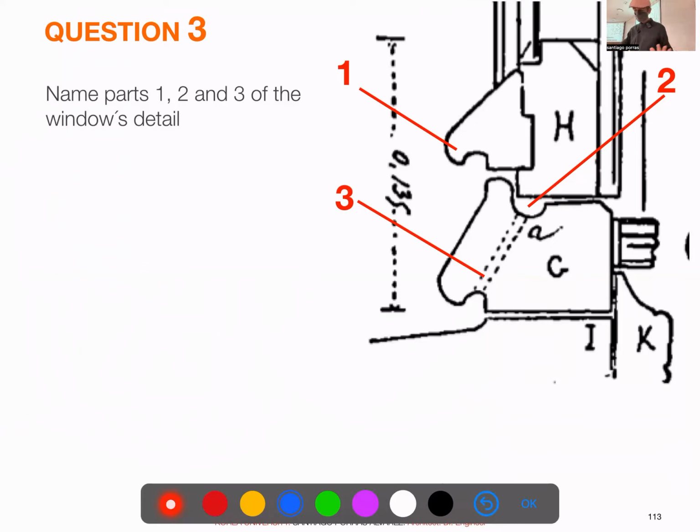So I would try not to touch much, but see the glass, right? With this kind of small things, probably one nail there. So the glass is giving more, letting the water stay out to protect more the sash itself, right? Nowadays, as I said, we often put the glass inside. And then curiously, the dripper is an additional piece. It could be done in one piece, but probably this is just an addition to the sash, which is more or less the same on four sides. So they don't need to make a special piece for that. And that element here is part of the hardware, right? This is a metal element to have the opening and closing of the window.